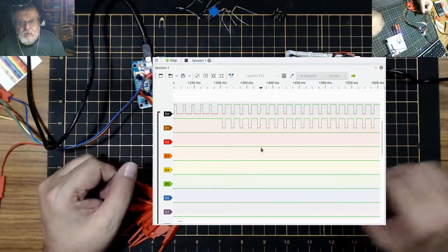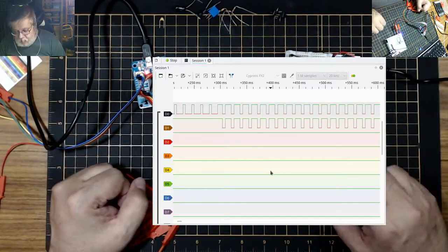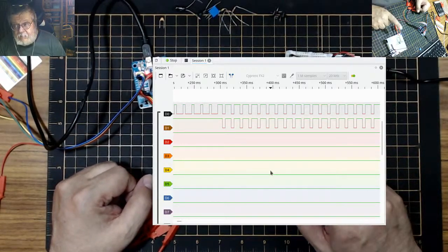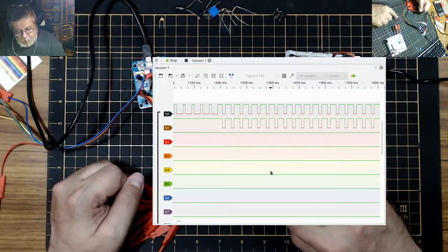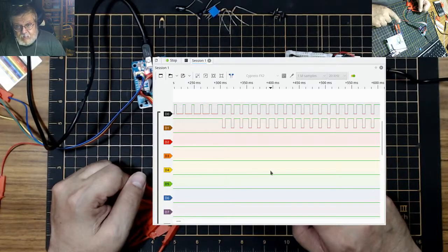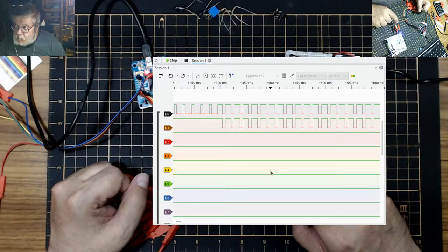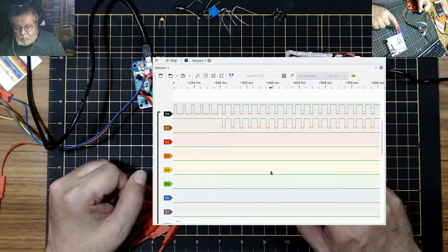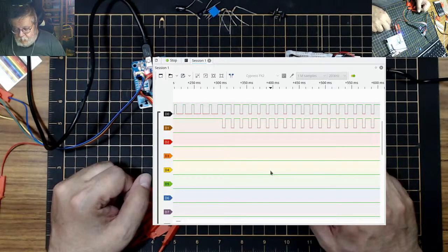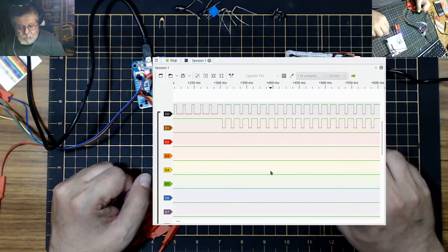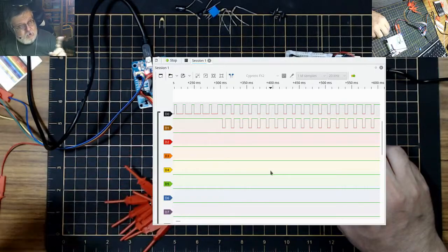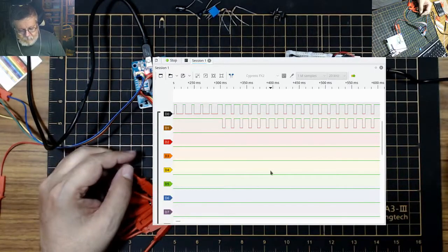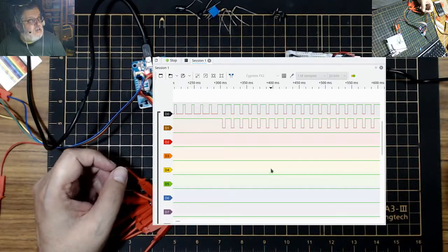So, our little logic analyzer. Now, I don't have this set up yet, but if I put a CPU down and I put one of these channels on every address line and trigger the CPU, let's say a 6502, to do NOPs, I should get the binary code out of there telling me what is actually coming out.